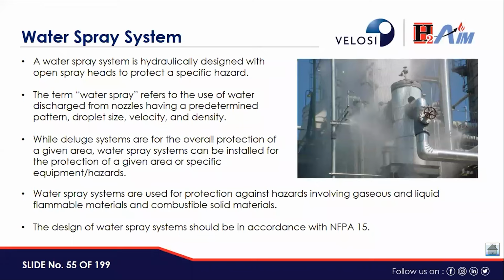While deluge systems are for the overall protection of a given area, a water spray system can be installed for the protection of a given area for specific equipment or hazards. This water spray system should be designed in accordance with NFPA 15. These water spray systems are used for protection against hazards involving gaseous and liquid flammable materials and combustible solid materials.